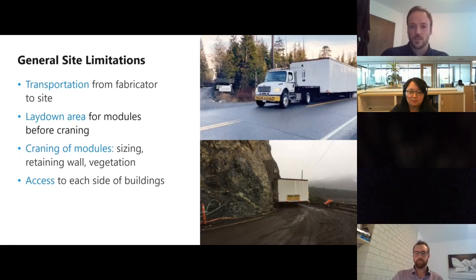We actually had a transportation study done for this, and the fabricator that we used was based out of Cumberland, but we also did it for fabricators on the mainland as well. Typically we would ship all the mods to a location within 5 kilometers from the site, and that would be our laydown area, which also has to be factored into the module sizing.